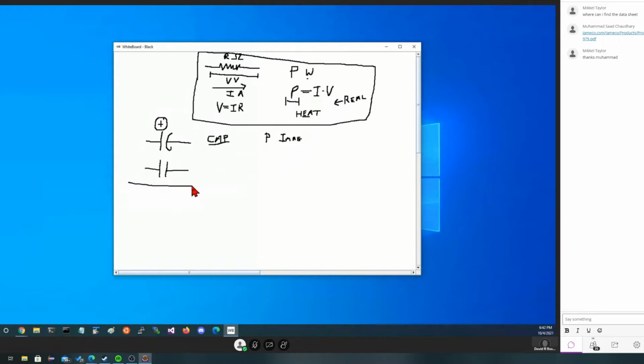This won't work for us, but it exists. Now, a capacitor has some rules and things that we're going to think about later, but basically, we're going to say the voltage lags the current. So while we can change the current that it looks like passing through this capacitor quickly, depending on the size of the capacitor, it's going to respond to the changes in current by changing its voltage difference more slowly. If it's pure current and pure voltage, the phase difference is exactly 90 degrees. We can talk about sine waves and cosine waves all day. We won't. We just want to think about this as resistant to changes in voltage. It doesn't want the voltage on it to change.